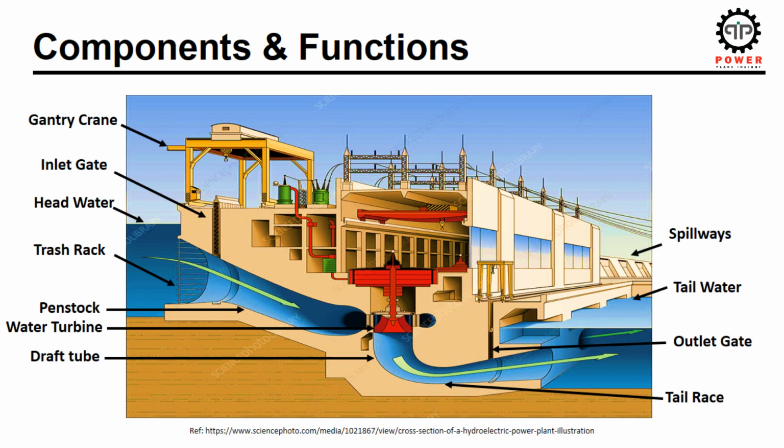Spillway acts as a safety valve in the hydel system, as the pressure safety valves are used in thermal power plants. It discharges the overflow water to the downstream side in a condition mainly arising during the flood periods. These are generally constructed of concrete and provided with a water discharge opening shut off by metal control gates. The discharge of the water to the downstream side can be regulated by adjusting the opening of the gates.